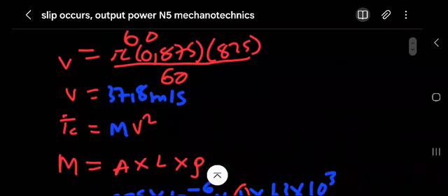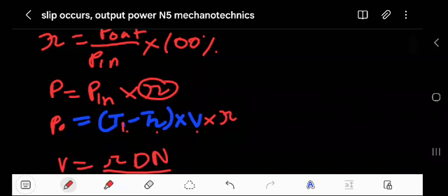Now we want to remember on our formula the aim. I've shown the aim is to find T1. We have T1 there, T2. Velocity already we have. If we can get T1 and T2, it will be sorted. So how can we get T1 and T2? T1, according to what we've been given there. Remember, we've been given tension per belt. So there's this area we must know, tension per belt, which is the stress.